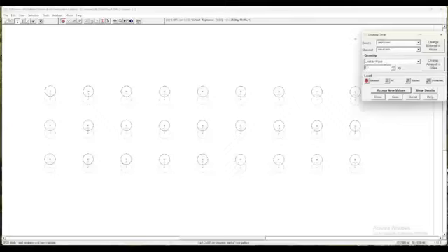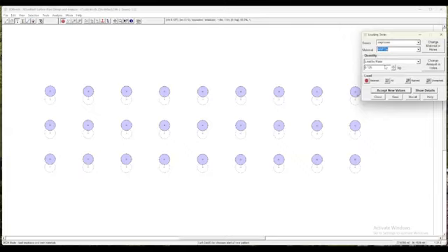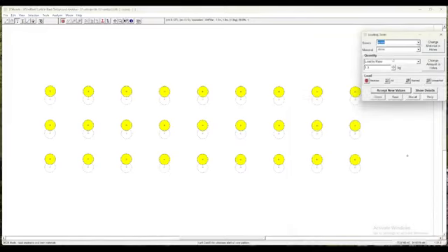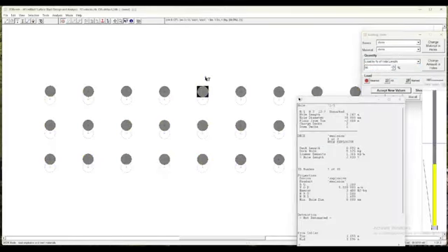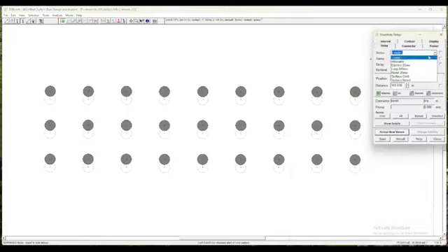After configuring all 6 design variations, we ran the blast simulation to generate the predicted results. The output showed fragmentation curves displaying the proportion of material below 300 and 400 millimeters. It also plotted air blast pressure and peak particle velocity graphs, helping us assess both performance and environmental impact. Through repeated simulation and adjustment, we identified Design 4 as the optimum model, achieving the best fragmentation, lowest vibration, and acceptable powder factor. This process clearly demonstrated how digital simulation tools can minimize trial and error and improve the precision of real-world blasting operations.